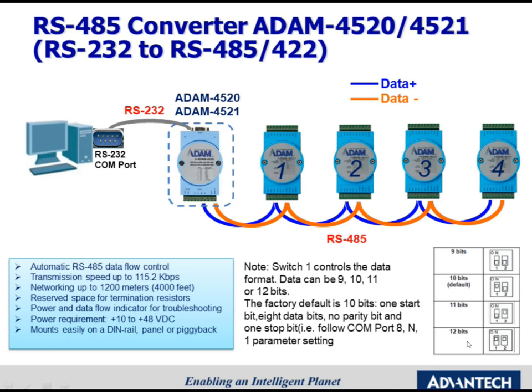We need to use the correct DIP switch setting on ADAM to communicate with the RS485 device. We will introduce the data format and the baud rate in more detail in the following slides.